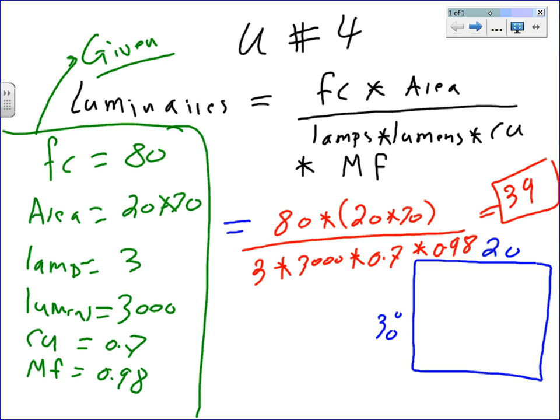You're going to start with a room in the software. Here's the software, here's a room. How am I going to start placing my fixtures? I know I have to have 6 fixtures. How am I going to put these fixtures physically, mechanically, so I can give it to the electrician, and the electrician will move, say, 4 feet from here and 6 feet, and put the first fixture center right here, and continue.